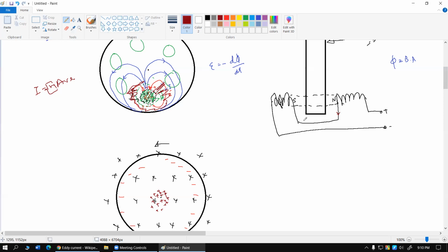So that actually helps to reduce the velocity of the vehicle in a very comfortable manner. If they're trying to maintain uniform deceleration, they're going to start with a pretty small current when the vehicle is moving really fast, where this disc could be directly attached to the wheel of the vehicle. At a high speed, even if you apply a very small amount of current, you're going to lose energy pretty fast because of the high rate of cutting through the coil.